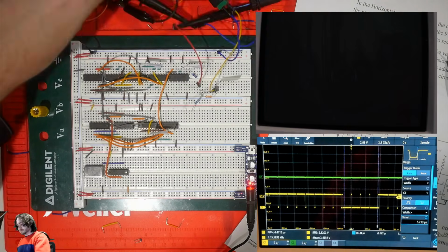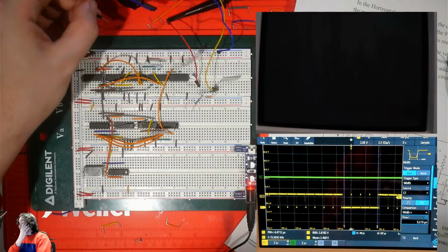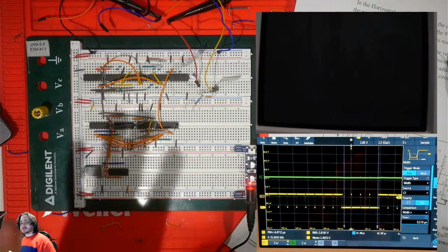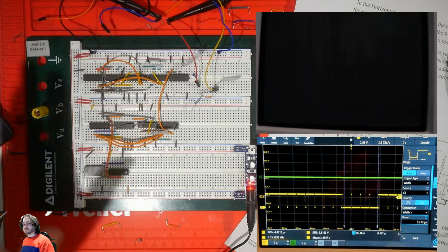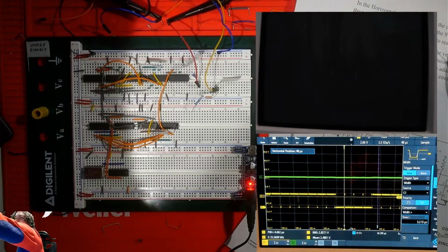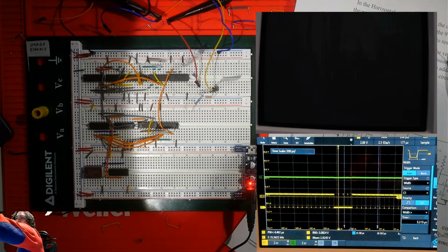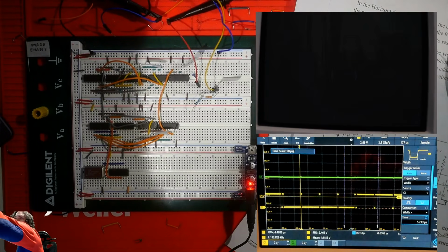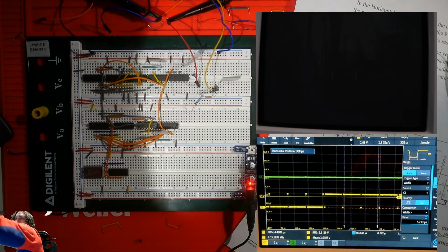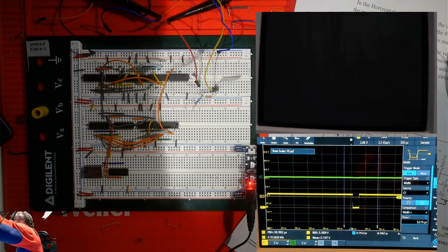Pull the second probe out for this. So now we're going to want to make a lot of our measurements relative timing-wise to the synchronization pulse. So if we do this, I can zoom us into a scan line. Each of these dips here, between those is one scan line of the TV.